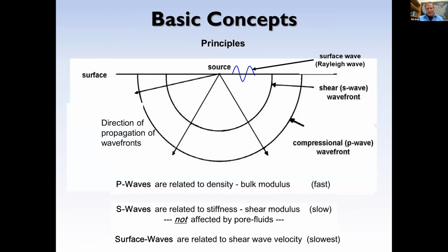But think of this slide as you just threw a rock into a pond. Those waves all go out in an entire hemispherical kind of way in the water, and then in a circular way on the surface. Well, that's what's happening when we spank the ground with any kind of source. What we do, though, is put receivers on the ground, and so we see it in plane or plan view fashion beneath those receivers. I've already mentioned that P waves are related to bulk and shear waves related to shear modulus,